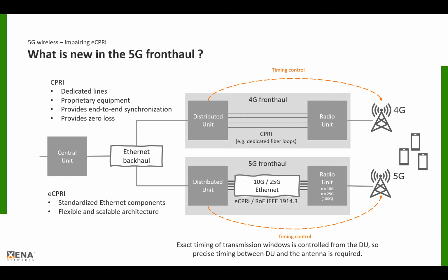Because 5G networks are large installations, they are costly to design, build, and operate. It is important to test the robustness of the entire installation before it's installed and put into operation. One way of making sure that the design from the DUs to the RUs is robust against the imperfections of the Ethernet fronthaul network is to replace the fronthaul network with an Ethernet emulator to do well-defined testing in the lab before rollout.